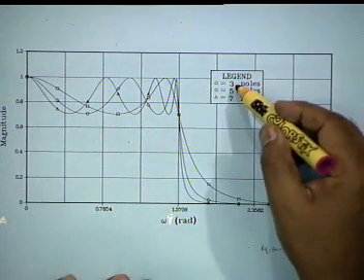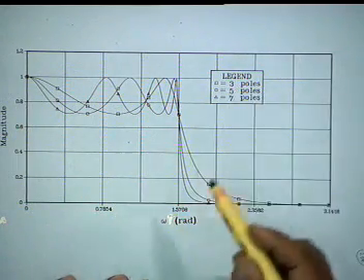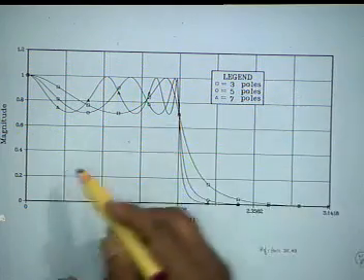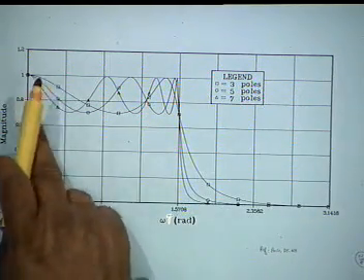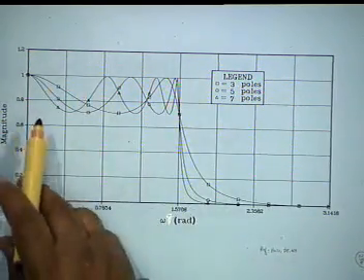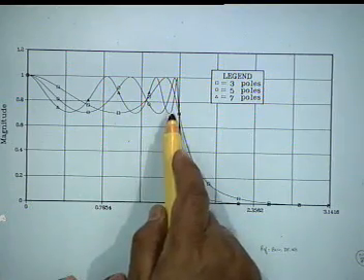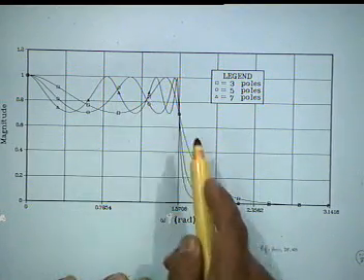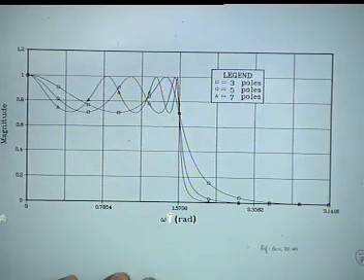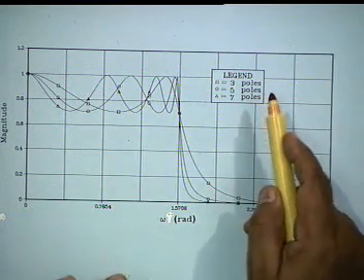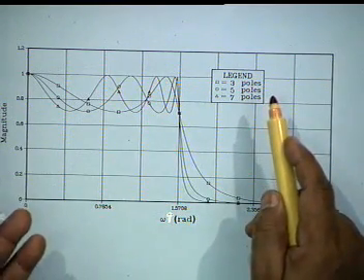Minimum order is 3 poles, and that is shown by the rectangles. You see the equal ripple in the pass band, minus 3 dB corresponds to 0.707. So, the lower line is here, the upper line is here. For 3, there are 3 peaks and dips. On the other hand, for 5, the number of oscillations increases.